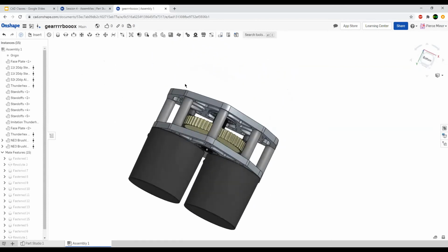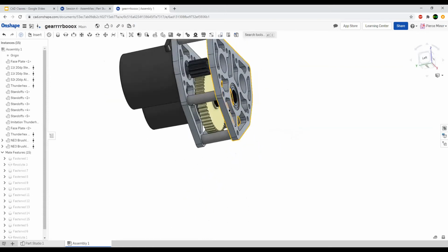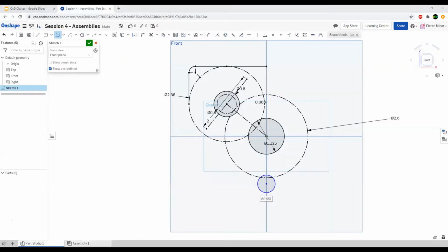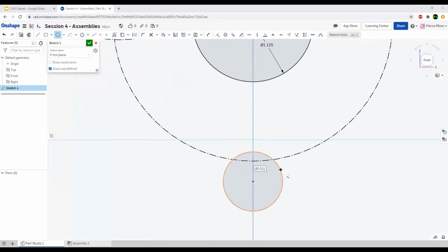But I just need various points around here, so this is going to properly hold itself together under any force it's under, or even its own forces. So basically, I need a hole down here, and I am going to have a certain perimeter around the hole that I can use to determine how large it needs to be, so I actually have enough material around the hole to make sure it doesn't break out or something.